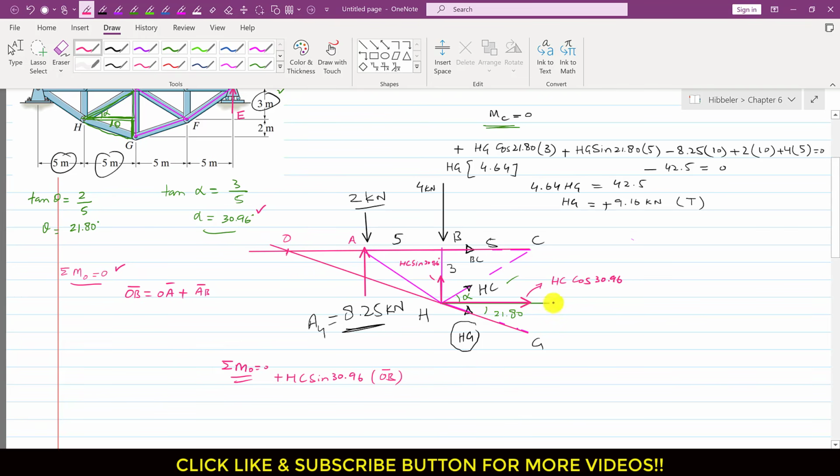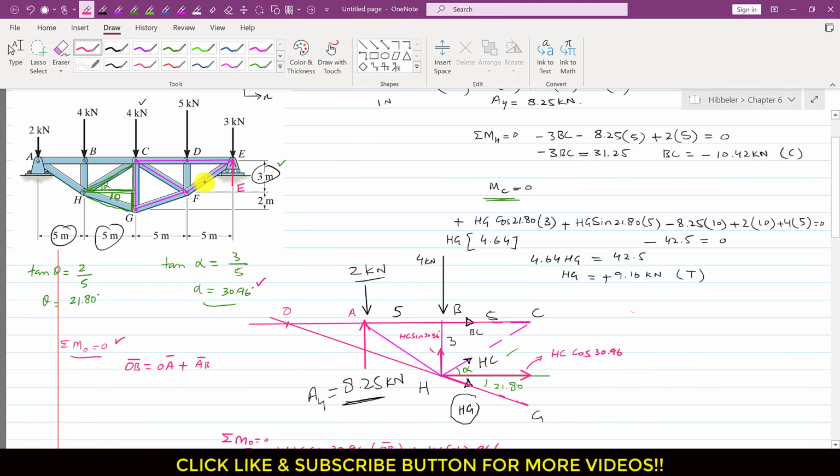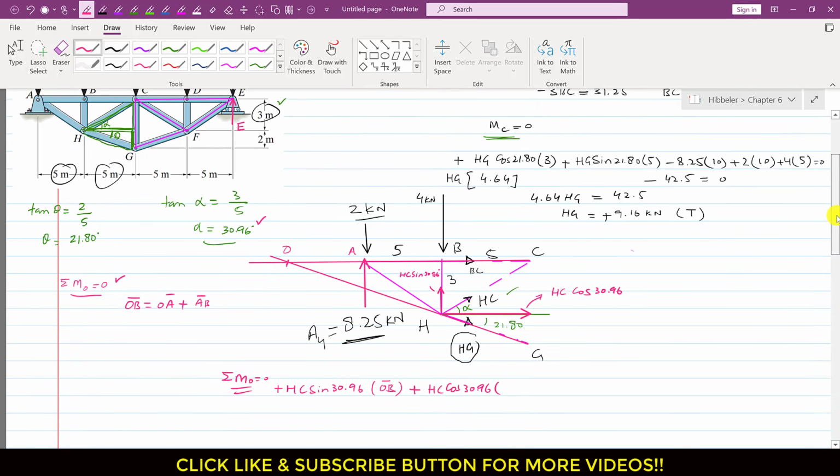Right? And again, this cos component is producing the counterclockwise moment about that point O as well, so I have to write plus HC cos of 30.96, and the perpendicular distance of this cos component from that point O is the length of this BH member, and the length of this BH member is 3 meters, right? We know this already.